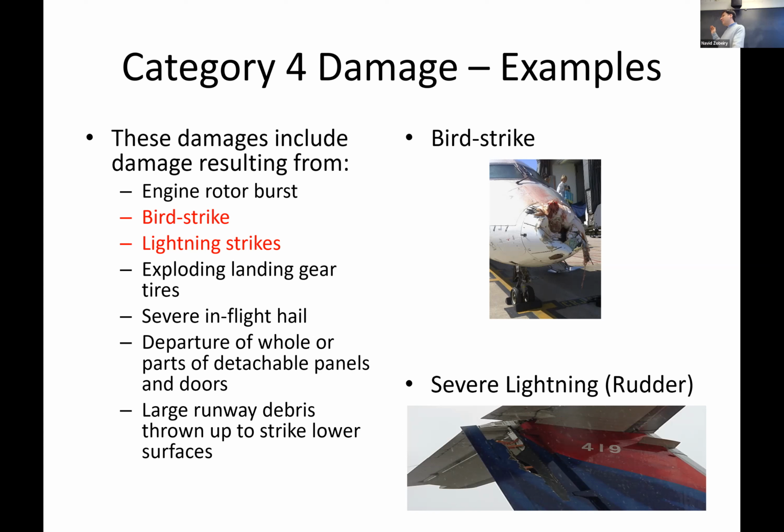Upon this, they will immediately reduce the flight envelope. They will immediately start reducing the altitude and they can safely land the structure and then repair it. So you have to design the structure that even with these defects, it can safely fly, but with a reduced load on the structure, right? Again, this doesn't exist for metals, but you put all of these severe punishments on composite because we don't know what type of impact load comes in, right?